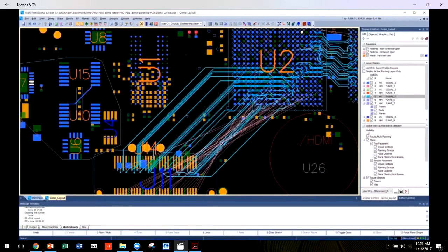And if you plan on doing manual tuning, you should consider using the unpacked style because the traces will be spread out. When using unpacked, the algorithm prioritizes reducing segments as opposed to packing the routes along the sketch path.